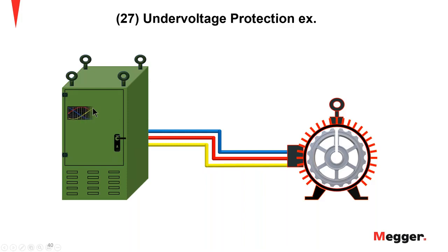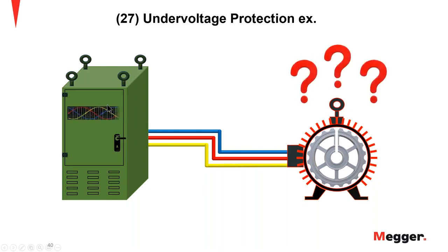So you can see here that we have a low voltage scenario now happening. We're delivering power to the motor, and of course the motor can't start because the power is not up to where it needs to be. Most relays look at 80% to 100%, I think with 80 being the low end, from what I've been working through. It does take a minute to troubleshoot, and it still costs you money because this thing's down and you're having to troubleshoot your cabinet now, or your power supply.